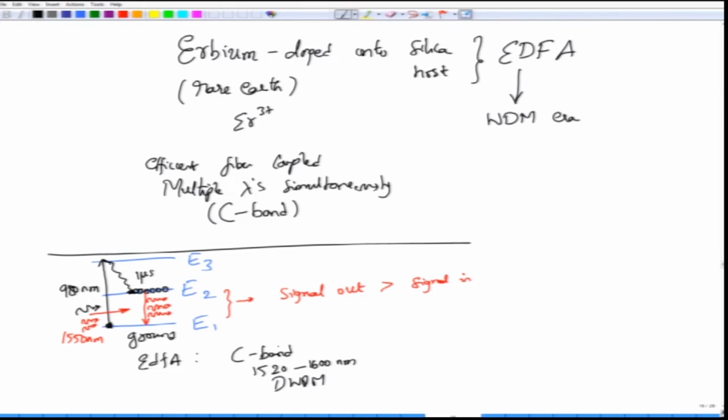Now, you know from our discussion on a laser that there are three components to a laser. So, there is actually an amplifier in between. This amplifier is what we called an active medium. Active medium is the one wherein we can create a population inversion. So, erbium doped fibers are equivalent to an active medium, because when you pump these erbium ions, these ions will jump through the indirect process and create a population inversion between the energy levels E2 and E1. Okay. So, you have an amplifier or an active medium which is anyway there.